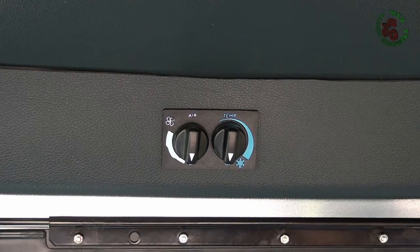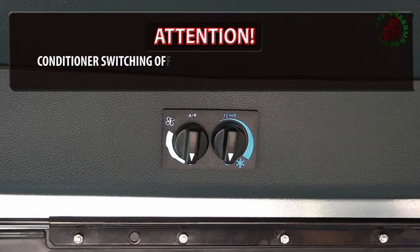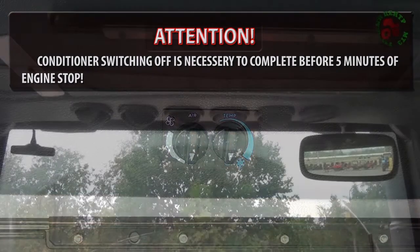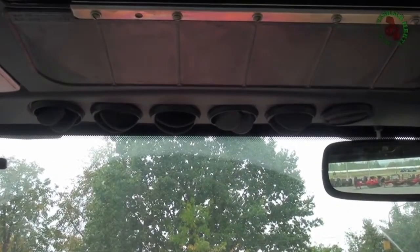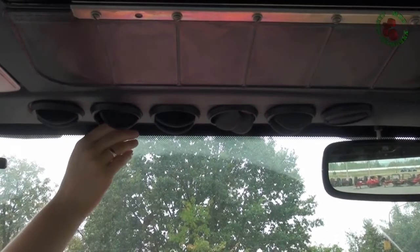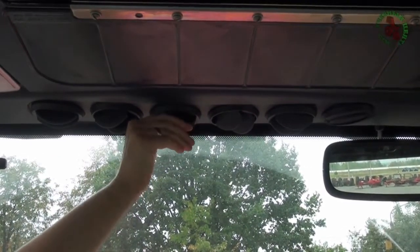For reliable conditioner operation, it is essential to remember that the conditioner switching off is necessary to complete 5 minutes before engine stop. Near the front windscreen located 6 deflectors. By turning the deflectors, air direction in the cab can be achieved.